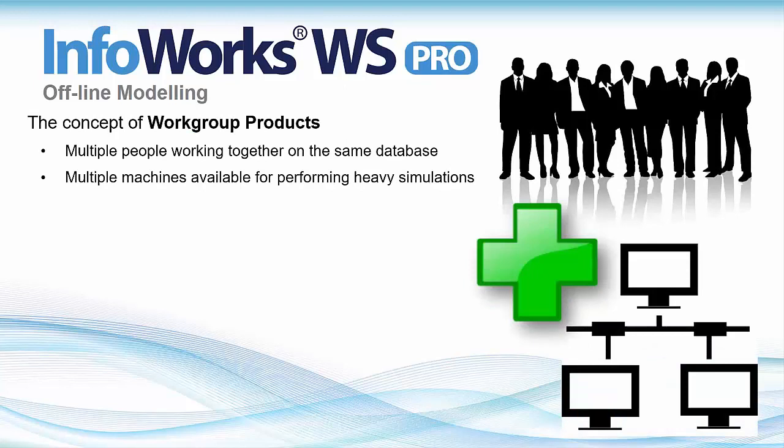Just to mention a few things, InfoWorks WS Pro is the replacement of InfoWorks WS, and in InfoWorks WS Pro we adopted the latest computer technology, which allows the step further that I was mentioning before in hydraulic modeling. This is because InfoWorks WS Pro is a real workgroup product, and the main enhancement is that you can have multiple users working at the same time, and it also allows multiple distributed simulations across a pool of dedicated simulation machines, what we call remote agents, that we can use to perform simulations quicker. And it does have network database and result sharing as well.